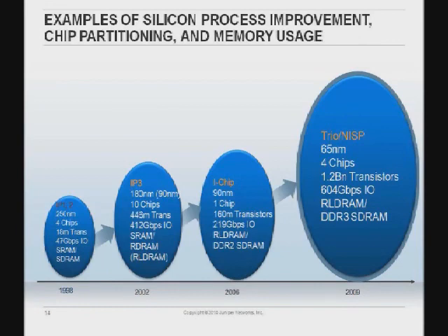And that was a 9-chip complex. We combined one of the interface chips because we were like 2 generations ahead. At that time, we still used SRAM as a control memory, and we switched to RL DRAM, the reduced latency DRAM, as the packet memory. DDR SDRAM at that time wasn't mature, and its performance was not up to par, so RL DRAM was the best we could use.